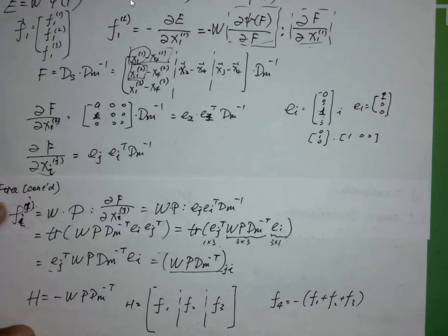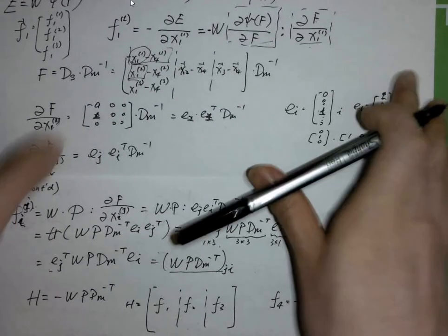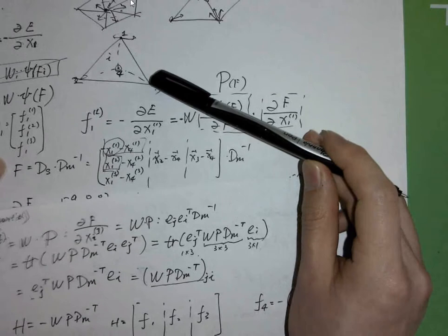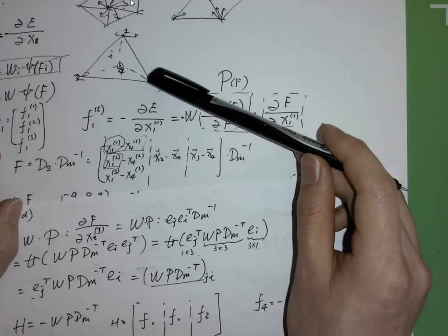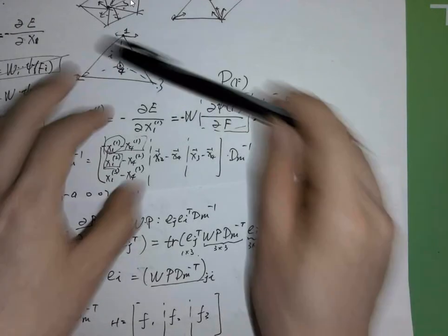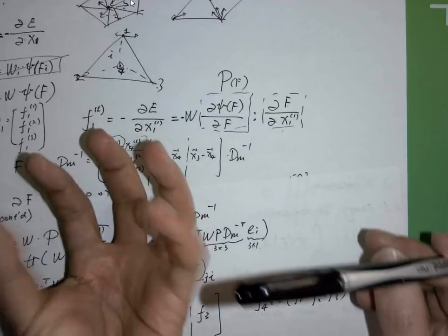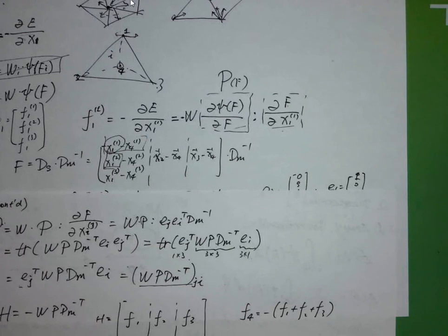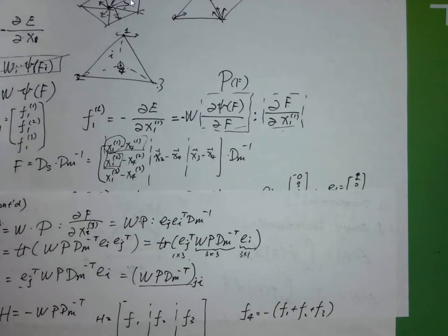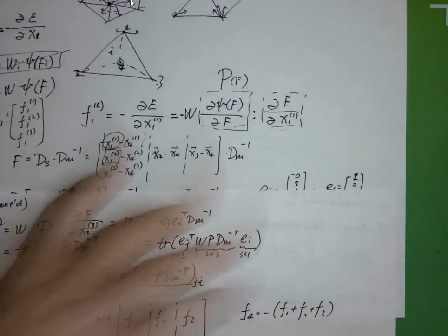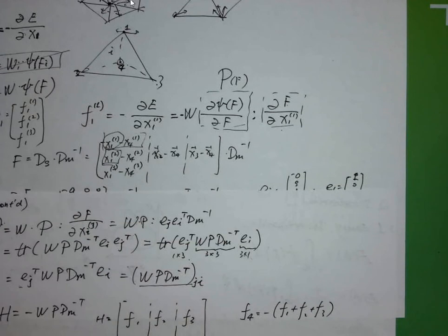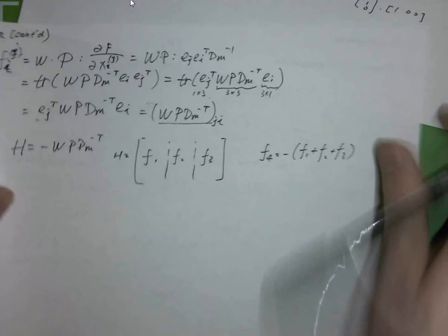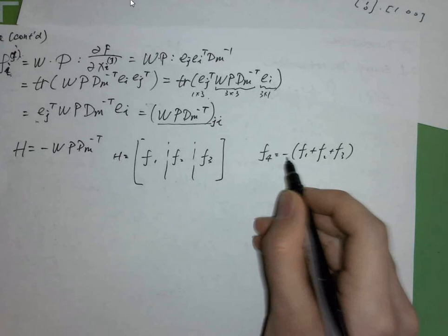That makes perfect sense because for one linear element, we also want to preserve its linear momentum. So the force acting on all 4 vertices together should equal 0, because by this internal force there should not be any force to move the entire element somewhere else, right? So it's super intuitive to say F4 equals the negative of the summation of F1, F2, F3,